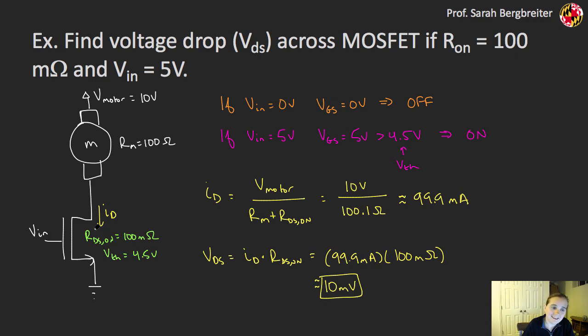So I can have a much smaller voltage drop in a MOSFET, which is one reason that people sometimes choose a MOSFET to drive a motor. It's also pretty small, which is going to be putting me in that linear region, so my assumption that I get this drain source resistance and it acts as that nice resistor there is valid.